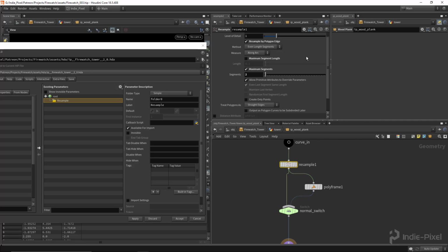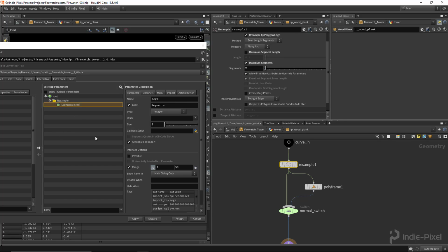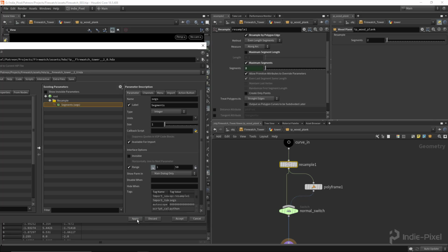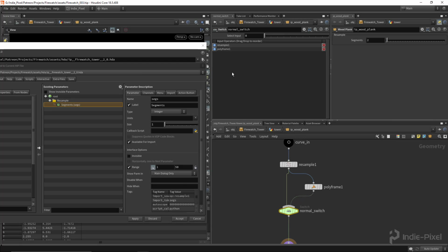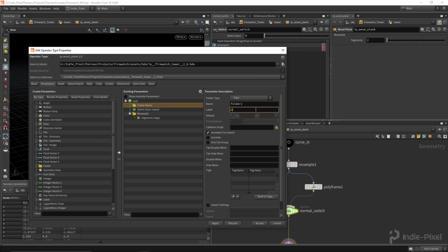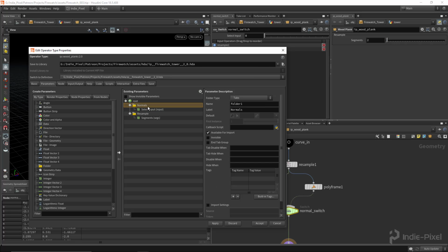So let's promote our 2 things here. So I have my segments. So there we go. So we want segments. That's actually a good name for it. Yep, I think the defaults are fine. So we'll just leave it at that for now. And then we also want to promote our switch here. So I'm just going to drag and drop this guy out here, and let's put that into another simple folder as well, and we'll call this normals. Let's capitalize that to be official. There we go. And I'm going to drag and drop that parameter into that normal folder there.